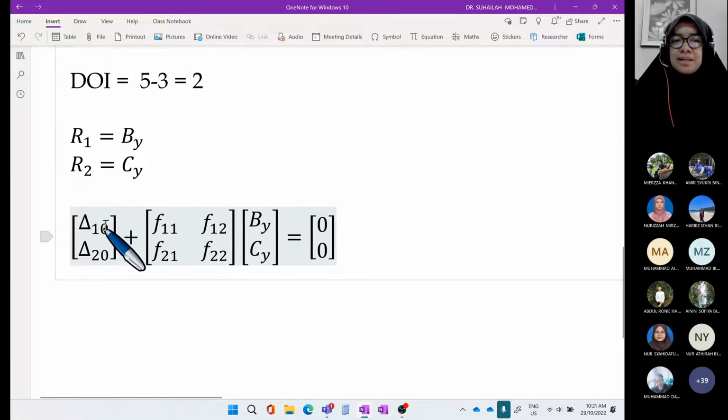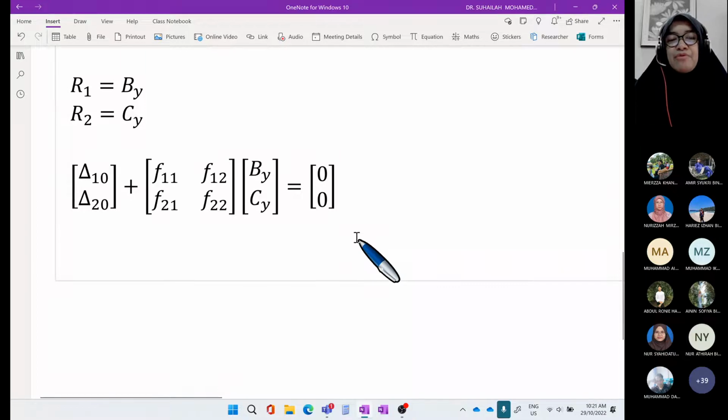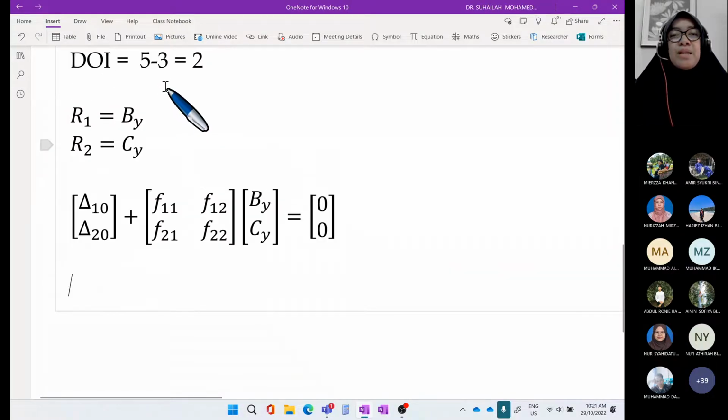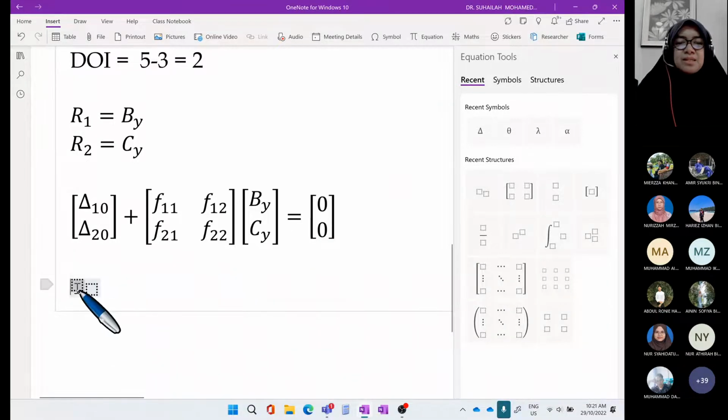The six displacements will be determined using the displacement formula. For beam and frame, we will integrate the moment equations. Not two moment equations, we will have three moment equations because we have two redundants. Two redundants, we have three moment equations. So we have six displacements, starting with delta 1 naught.